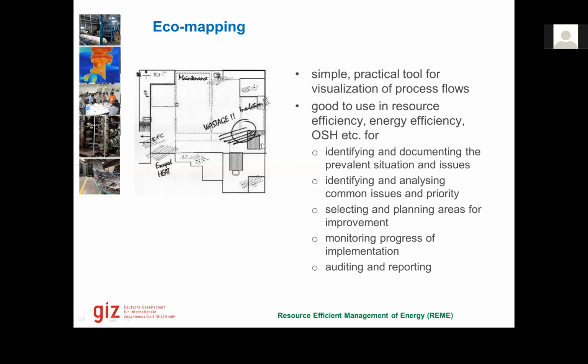So in this location, I say this location is A1, and in the A1 location, I have two symbols. One is a hatch line and one is a circle. So in this additional sheet, I would also write in detail what this circle means in A1 location and what this hatch line means in A1 location. So this is an advanced or detailed way we could also use this.